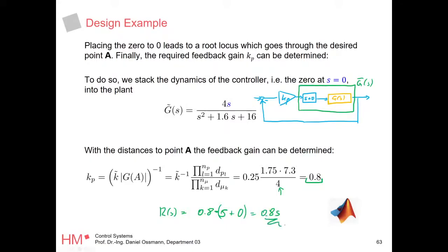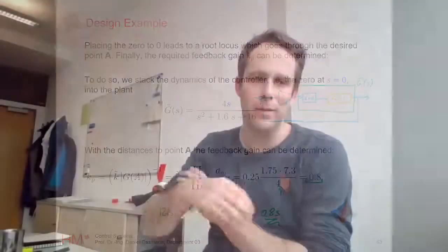And this controller is actually not a PD controller anymore, it's a pure D controller, which I told you is not really a controller, but it's actually pretty nice for that example. And it has a mechanical background why it's only a D controller. What is a D controller doing? It's basically taking the output of our spring mass damper system. The output is the position. The D controller makes of that position a velocity and feeds the velocity back, and the pure velocity feedback will only increase the damping and not the eigenfrequency. Okay, this is what this example actually confirms.